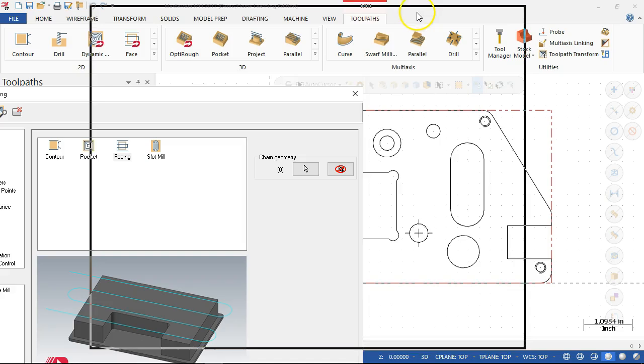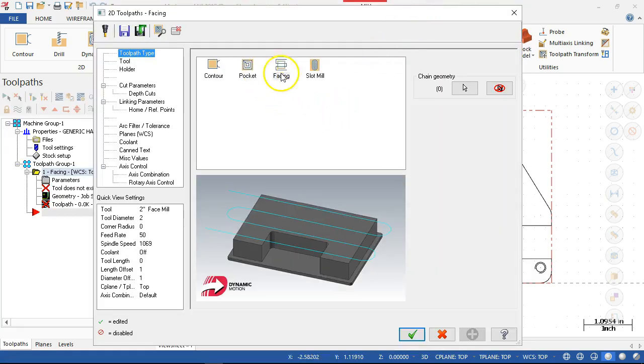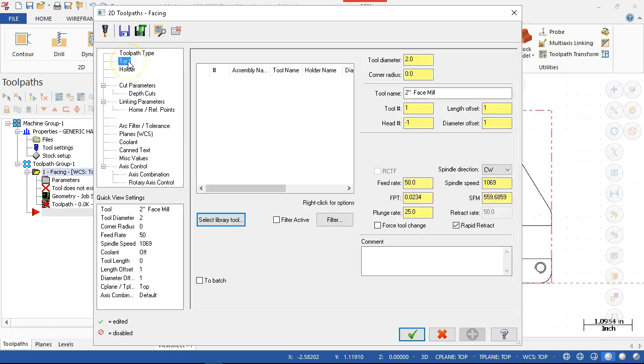All right, so on the facing operation, the assumption is that we're just going to go in one direction or work back and forth to clean up. Obviously, if I have a 5 inch fly cutter or larger, if I can take that in one pass and get a smooth finish, that's going to be my best bet. Most of the time, we're going to have a 2, maybe a 3 inch multi insert facing cutter. So we'll stay with the facing.